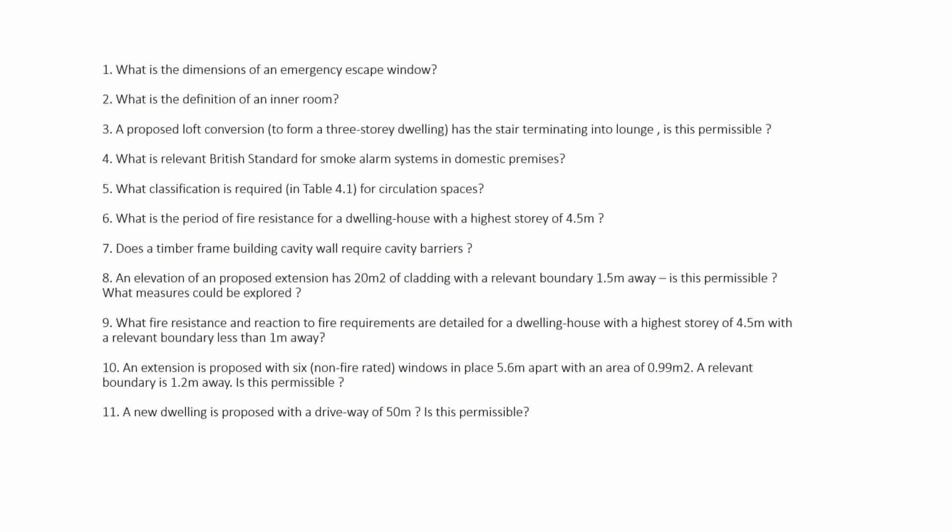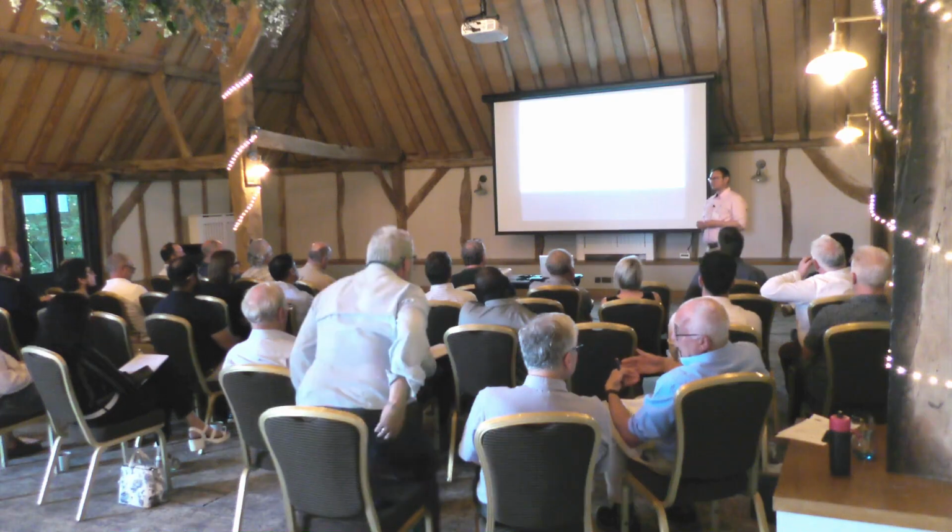Perfect, yeah, so the means of escape is only through another room, in essence. Proposed loft conversion to form a three-storey dwelling has the stair terminating into the lounge. Is this permissible? Yeah. Correct, yes, it could be, but you need to have additional measures.